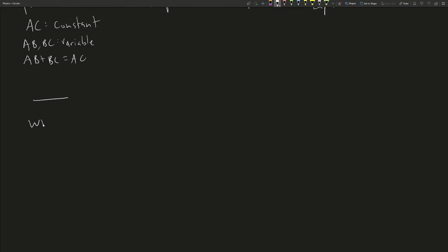Now there are also some circuit components such as, really basic, a line here. This is just a wire. So whenever you just see a line, that represents a wire. And whenever you see lines connected like this, usually there'll be a little dot there. When there's a dot connecting at the intersection of lines, this is a junction. So this just means that the wires are connected at that point. Whenever the wires aren't connected and they cross, usually you'll see them drawn like that, where there's a bump on it. This means that the wires are not connected.